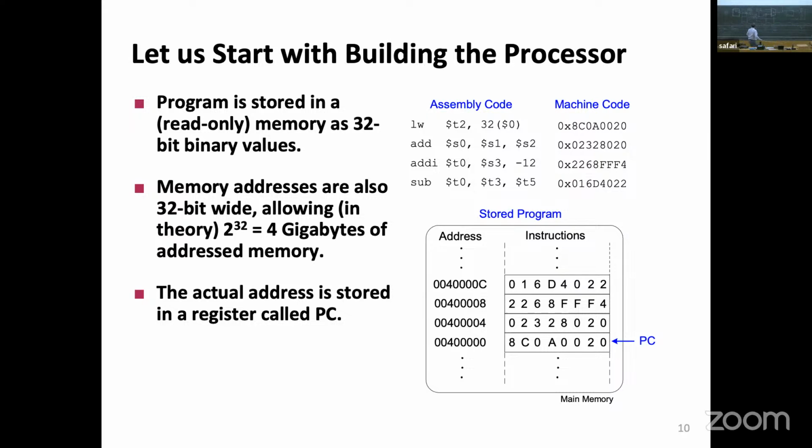In this case, once you see this, you will say the register destination should be 0. Register destination chooses which one of these addresses should be used to write back, the address of the register being written back. If it's a load word, it is 0, meaning that I choose this input of the multiplexer, instruction 20 to 16, meaning this guy here will be the destination. I will load the data into here.